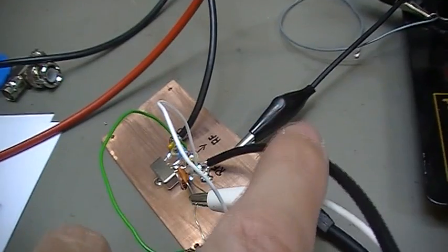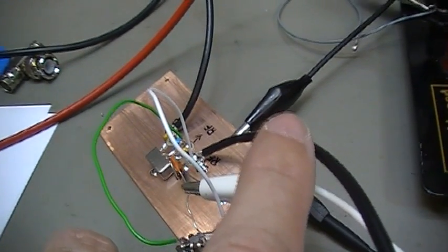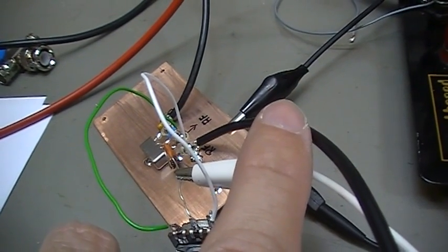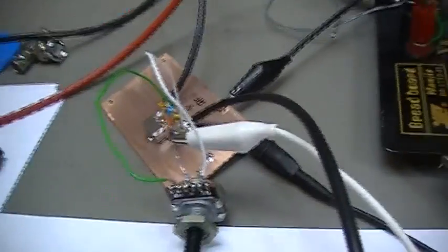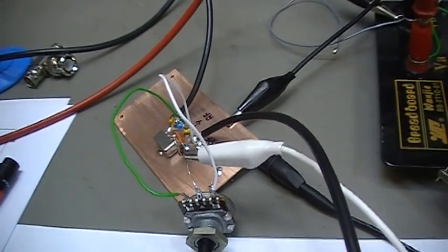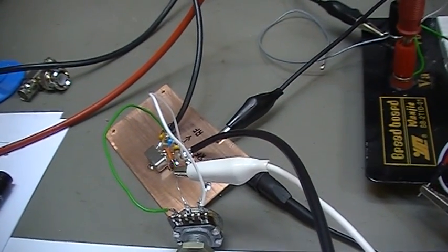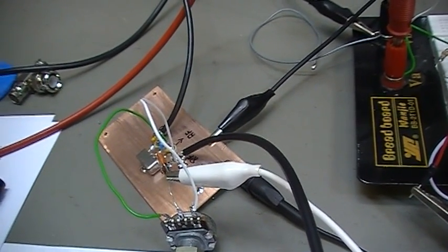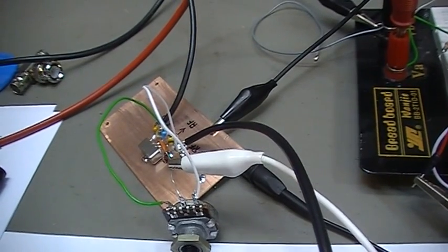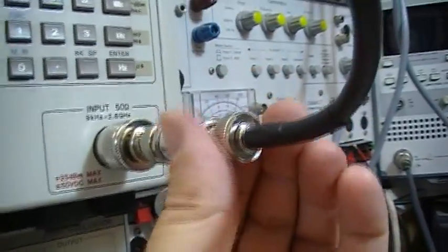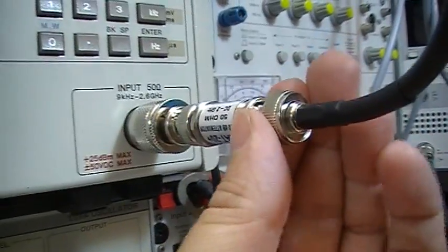That will be the level available when I'm testing a radio with 100 watt, because as I told you before, 100 watt is plus 50 dBm, and I have an attenuator in between which is attenuating this 50 dBm by 40 dB,